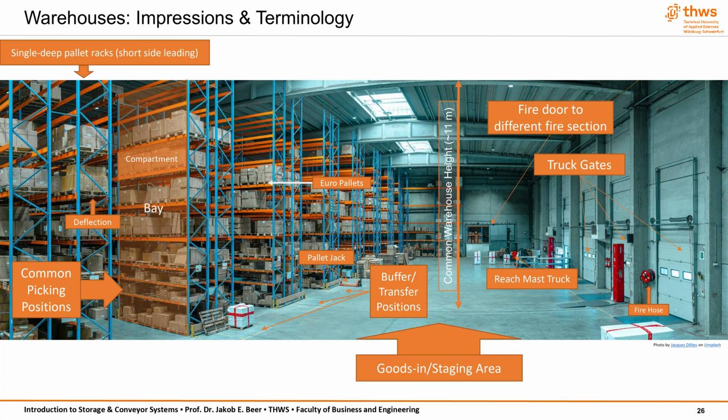There are several reasons why a pallet might deflect excessively. One key factor is how the load is distributed. If heavy items are concentrated in the center of the pallet rather than evenly across its surface, the bending stress will increase significantly. Another important factor is the material and design of the pallet. Wooden pallets are quite robust and can carry heavy loads, but they may weaken over time with repeated use. Plastic pallets behave differently.